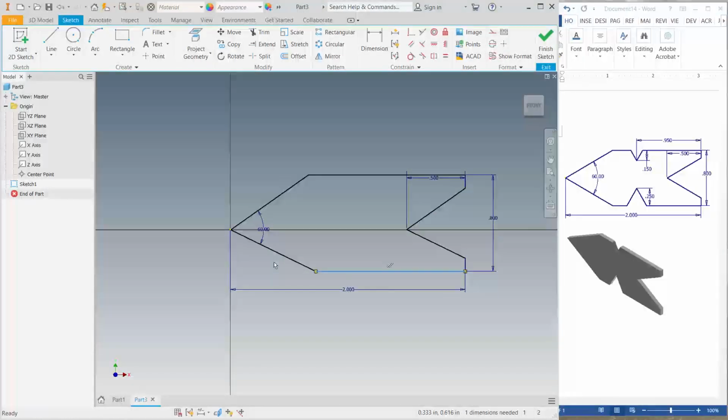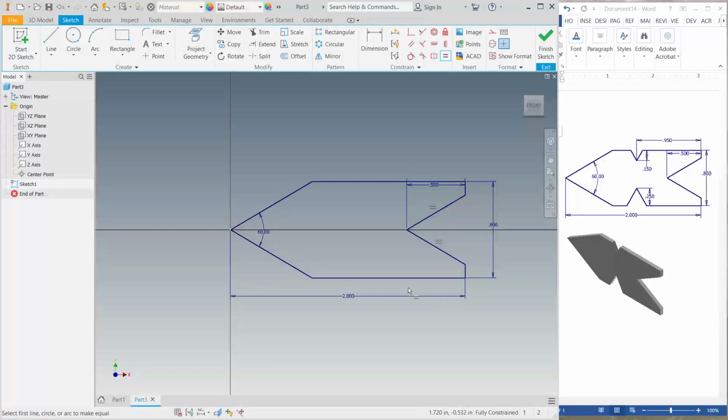This means, see here, they are not the same drawing anymore. They are not fully constrained anymore. So what I have to do is to repeat many things. So let me try this. This should be equal length. Okay. Now the minute I do the equal in here, you can see the color has changed into blue.